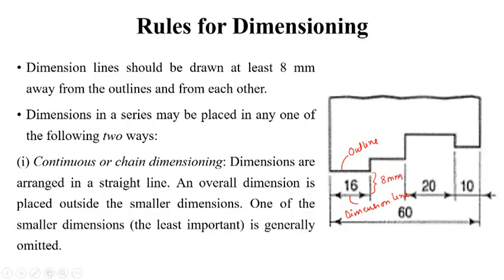You have to provide the dimension line at 8 mm distance. Again, between one dimension line and another dimension line, the distance is equal to 8 mm.